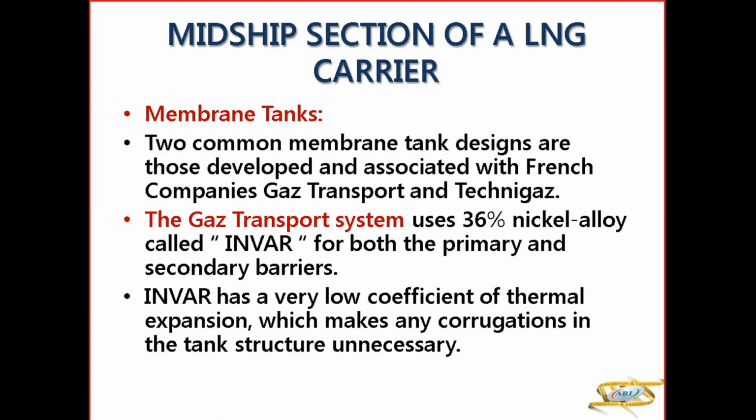The next type of tanks, which are typical for LNG vessels, are membrane tanks. Now, membrane tanks are very thin membranes, and there are two types. One is Gas Transport system, and the other one is Technigaz system. So these are two transport systems associated with French companies, Gaztransport and Technigaz, and their concepts are different.